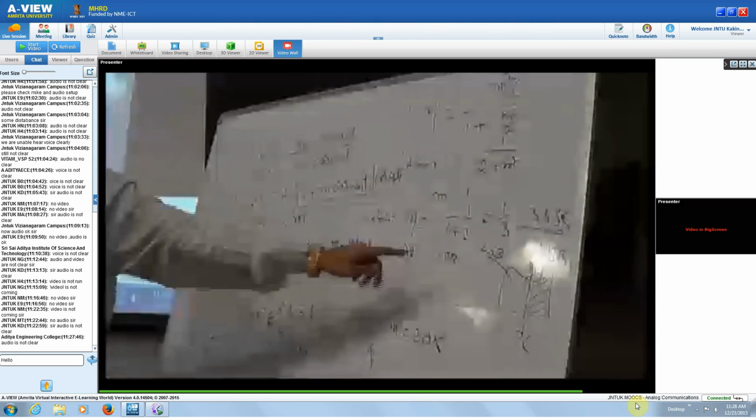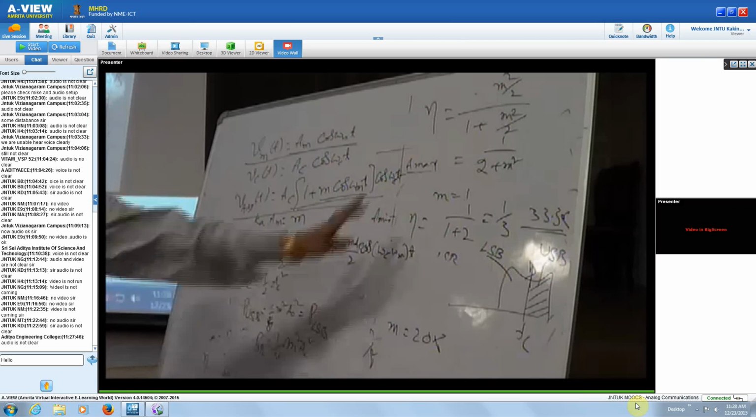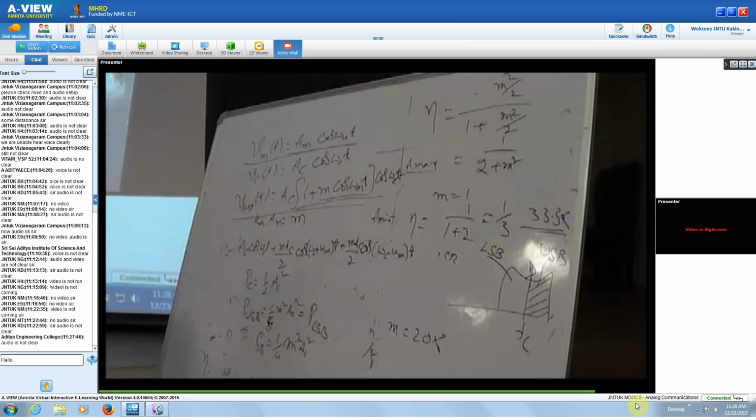Similarly for the double tone, you are going to have the average value of this m square t. Okay. So based on that, the modulation indexes we have to calculate accordingly, whether they are having a multi-tone or single tone or whatever signal we are going to have. So these are the relations between your modulation index and the total power that has been transmitted, along with A max and A minimum with the modulation index. So this is your amplitude modulation, how we are going to have the different sidebands and the total power.